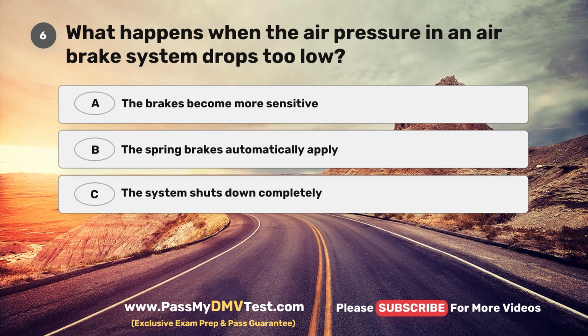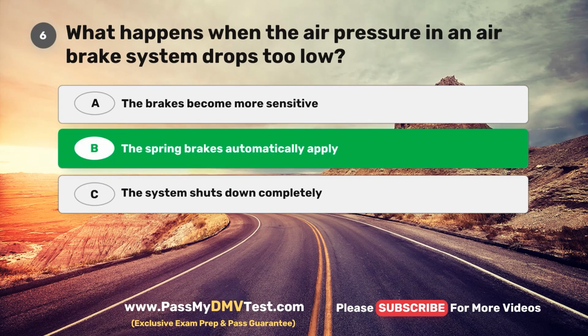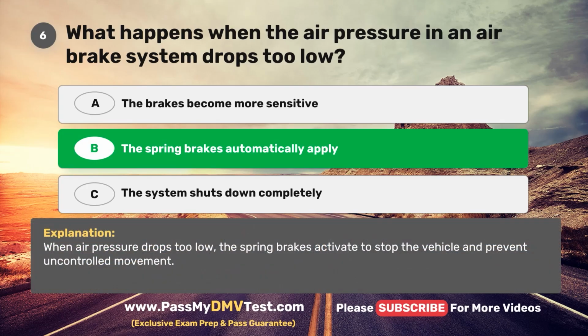Question 6. What happens when the air pressure in an air brake system drops too low? A. The brakes become more sensitive. B. The spring brakes automatically apply. C. The system shuts down completely. The correct answer is B. The spring brakes automatically apply. When air pressure drops too low, the spring brakes activate to stop the vehicle and prevent uncontrolled movement.